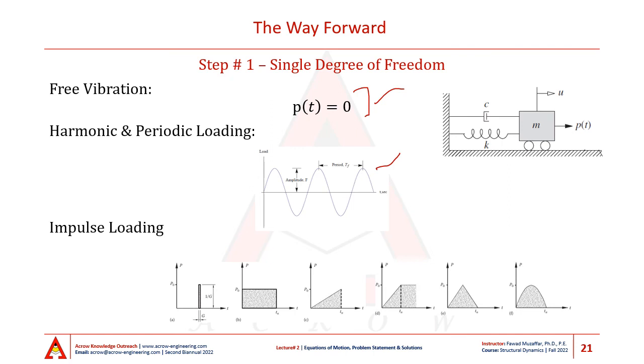Periodic loadings are any loading that repeats after a certain time interval T_p. Harmonic loadings are periodic loadings, but periodic loadings might or might not be harmonic. They can be any pattern of loading that repeats itself after a certain amount of time.